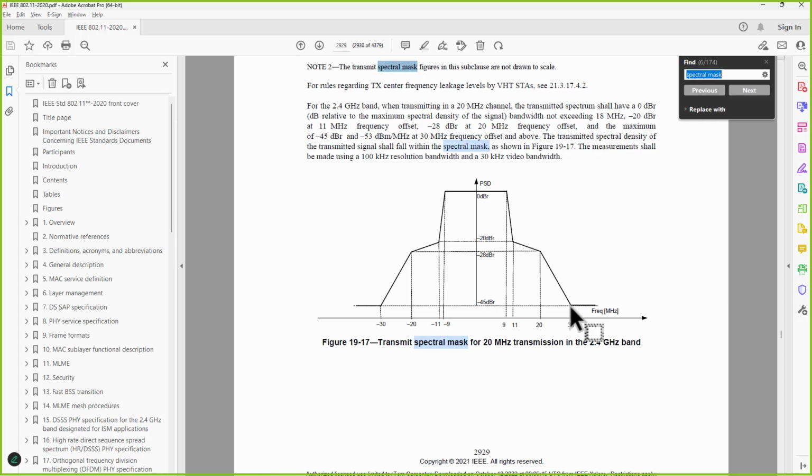This is the reality. Now you might say, oh yeah, Tom, but we're 45 dB below the signal by the time we get there. Yeah, and what is the normal signal strength for a signal that you receive? The normal signal strength for a signal that you receive is somewhere at negative 50 something or weaker. So maybe negative 51 or 52 or negative 63 or negative 70 or negative 80. And so, okay, negative 45 dB still matters, right?